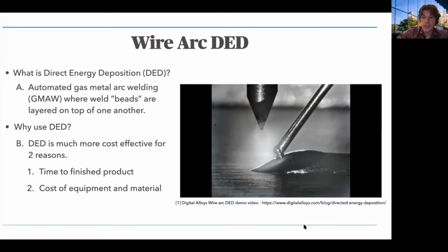So why would we use DED? DED is much more cost effective for two reasons. One, it takes less time to make product, so more products per same amount of time. Now, for this project, the goal is to try and make replacement components, not mass-produced components, but the amount of time to make a DED manufactured part, compared to trying to make a one-off cast part, as many of these pressure components are made, is a tenth the time.